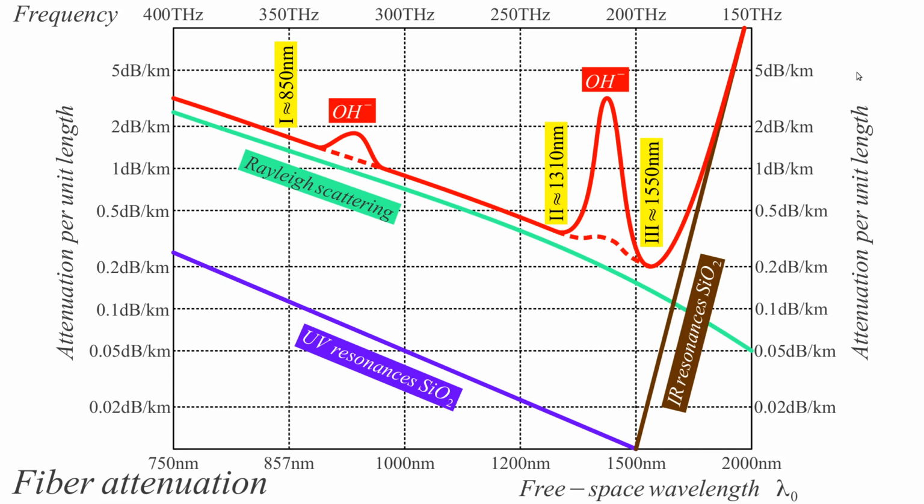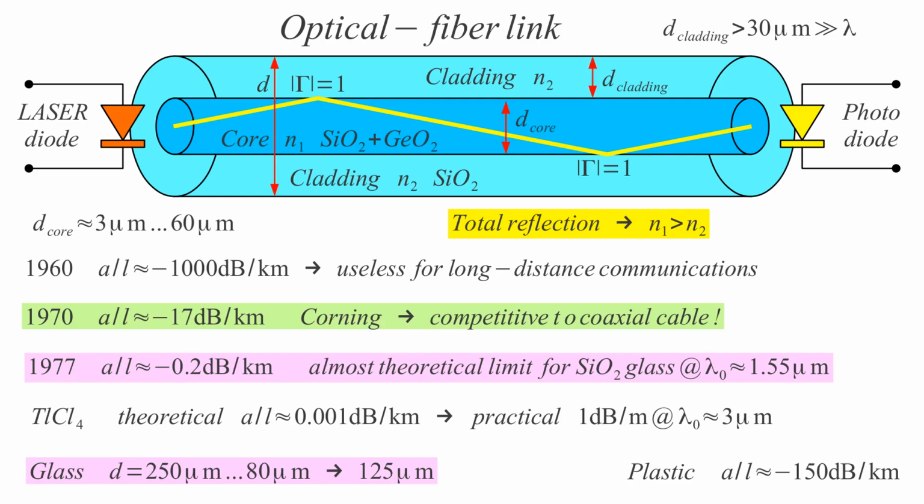So optical communications is nowadays used for long distance communication over cable, and since the prices of the hardware are going down, also for short range communications, for computer networks, also for Ethernet. The very cheap components are already here, but they are still more expensive than copper wire. The real problem is this diameter of the core. Even 60 micrometers is small and difficult for splicing. At lower dimensions, it's even more difficult to splice fibers.